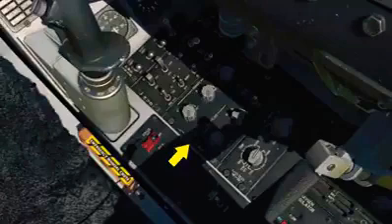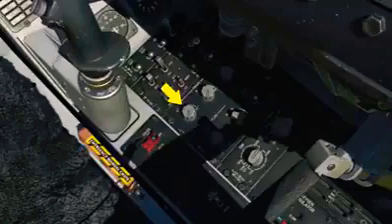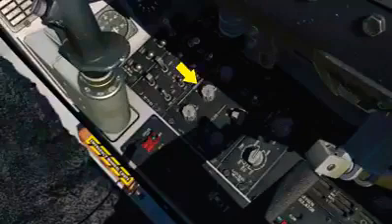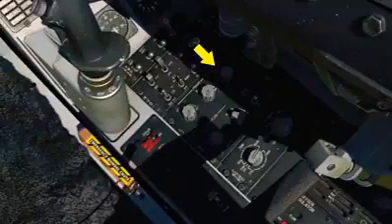The interior lighting panel consists of 3 knobs to turn on and control brightness in the cockpit. Most of the lighting is green to support night vision goggles. The primary consoles knob controls lighting of the left and right consoles. Primary instrument panel knob sets the lighting of the instrument panels and auxiliary panels. The primary data entry display knob controls lighting of the DED and PFLD displays.